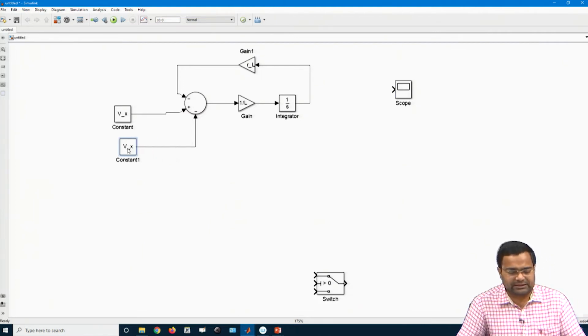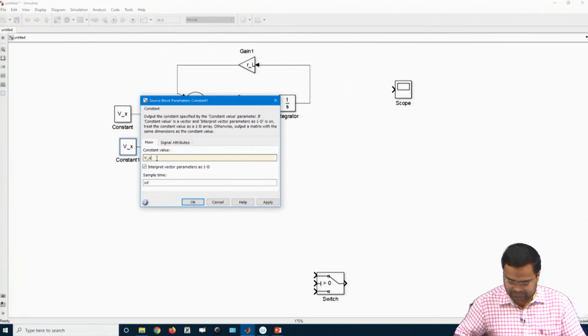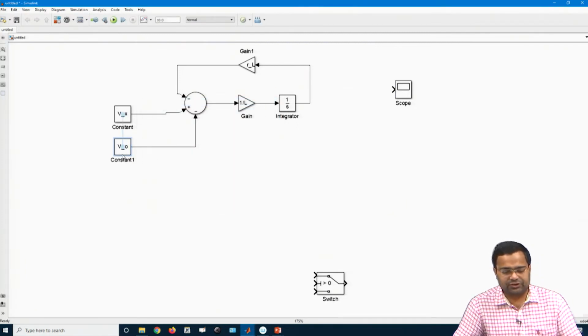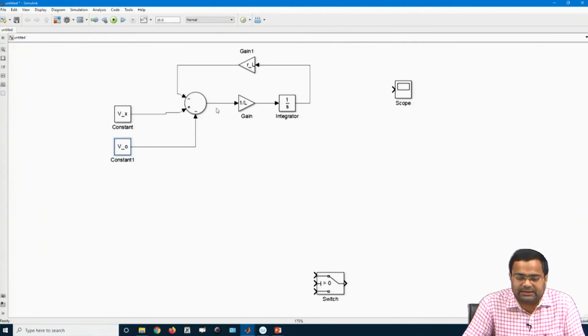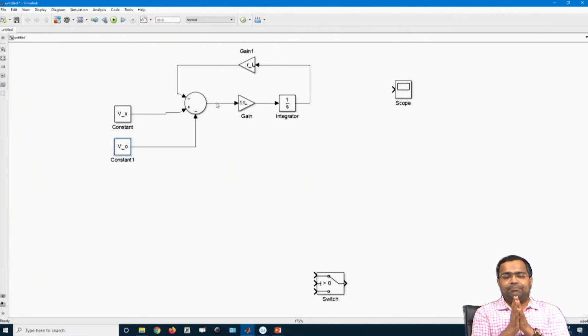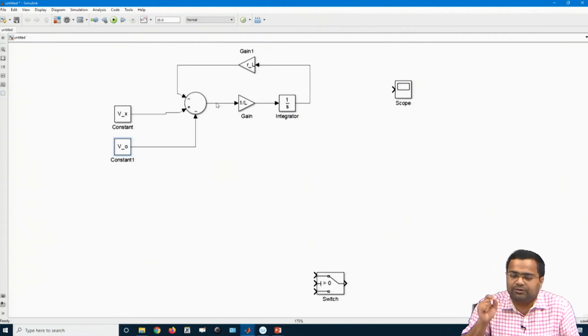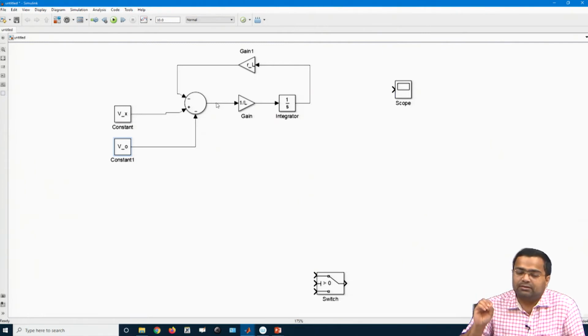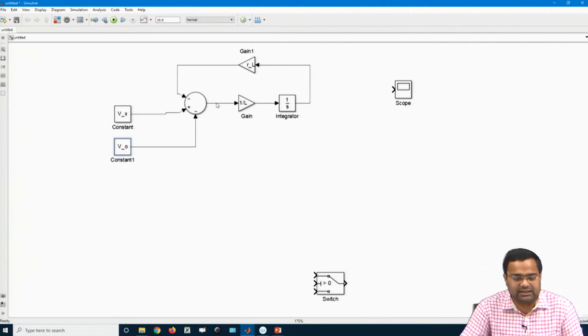Now, this is my V0, the output voltage. So, this will give me the inductor current dynamics, but as I said this is VL. The VL in general, when there is no discontinuous conduction mode, will be this one, but if we incorporate discontinuous conduction mode, the VL will be 0 when the DCM point is detected, zero current is detected and you have a diode. So, in that case we need to incorporate a switch.